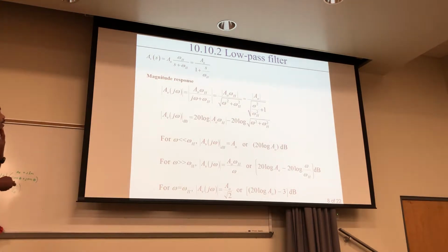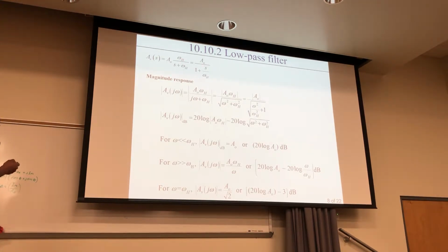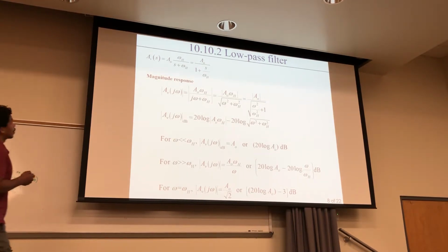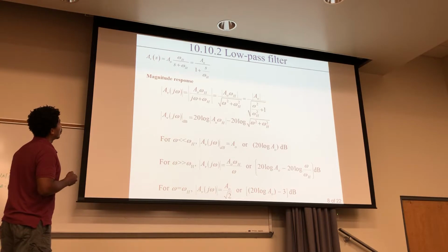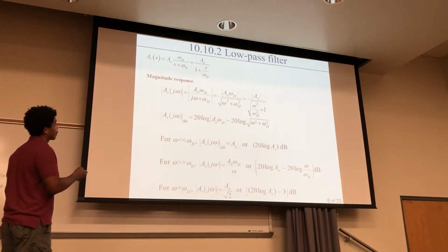Okay, so taking from this part right here, we examined some systems, but just taking a look at this, here's how you get the magnitude plot. What you're doing is starting from here, you're replacing the s with j omega, right? And then you take the magnitude of the whole thing, okay?